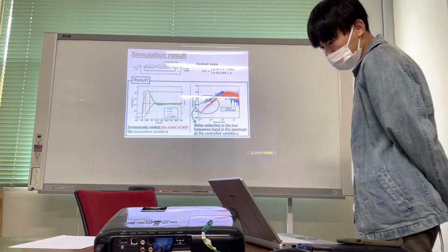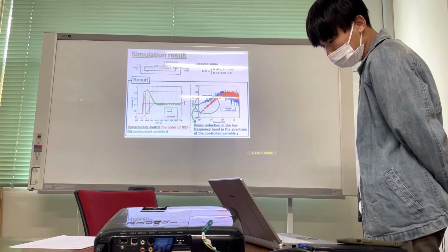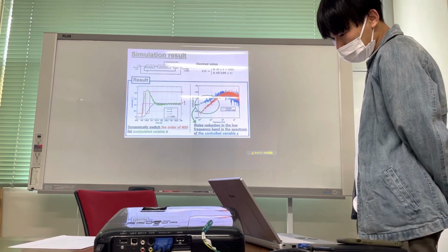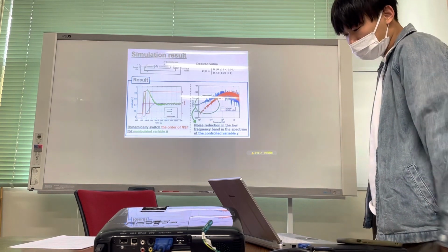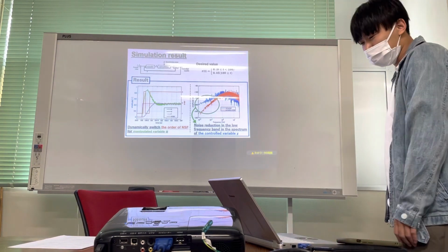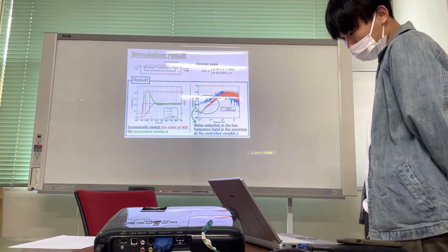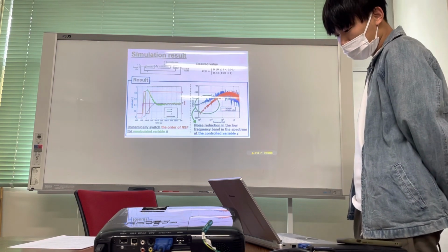As can be seen from these 2 results, the proposed variable order delta sigma modulator enables both entire operating range and high noise reduction performance, which were not possible with conventional delta sigma modulators.